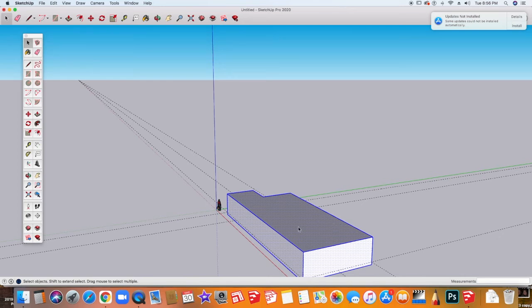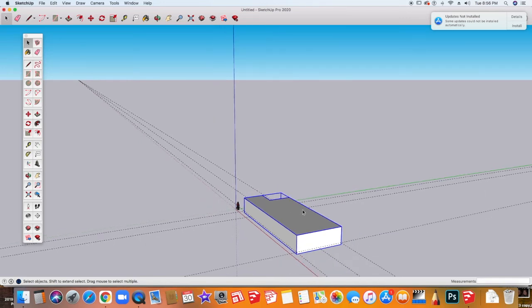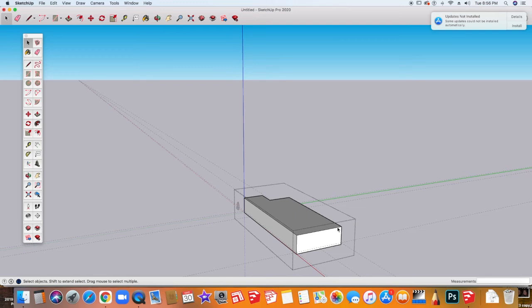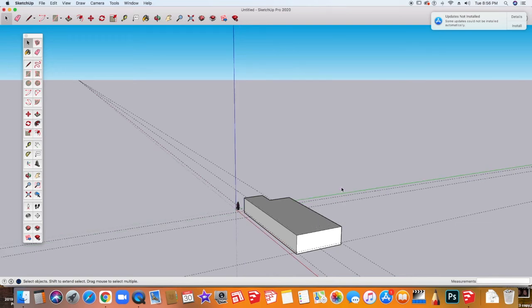Now I'm going to mouse over it and right click, and here I'm going to say make group. And you'll see that there's a line that automatically gets placed around here. That's just letting you know, a darker blue line, that it's a group. You can always go in and edit the group if you double click on the inside and you get this dotted bounding box, and you can move and change anything within the group, and then when you're done you just click outside of the dotted lines to close it. It's not obvious until you actually start to click on it.